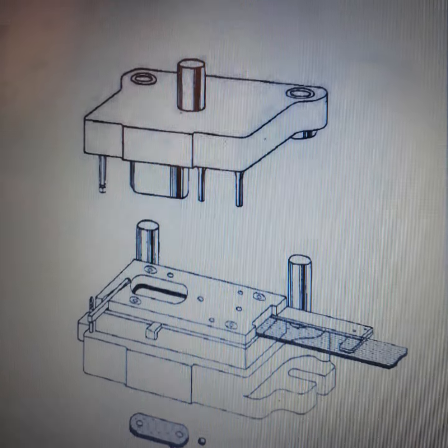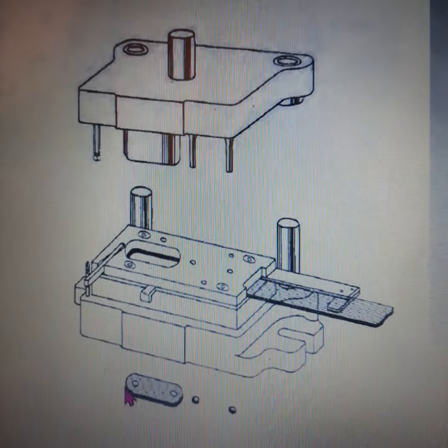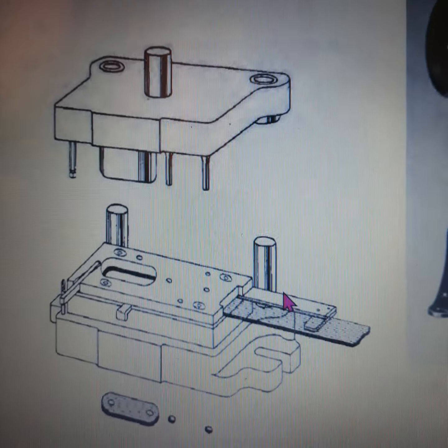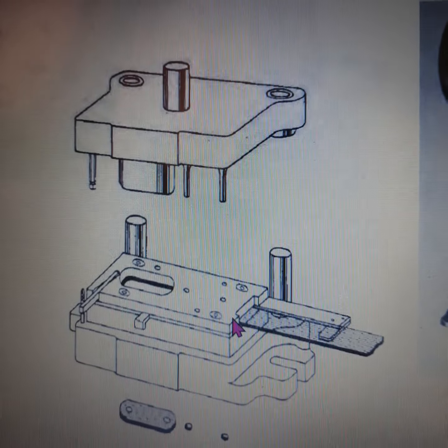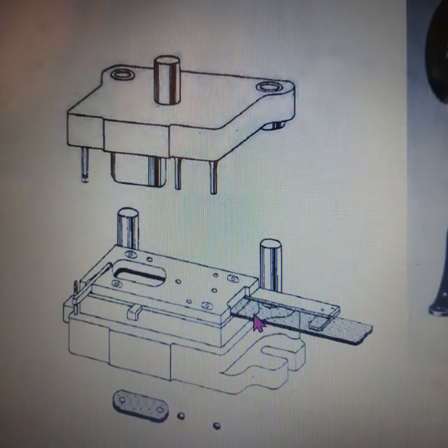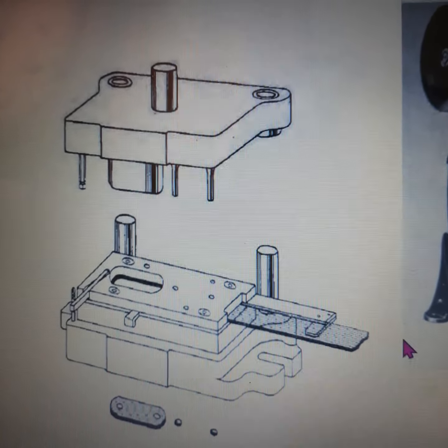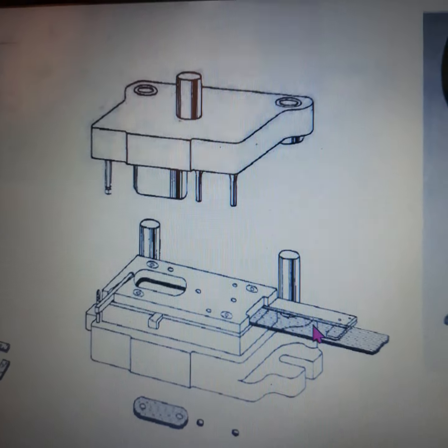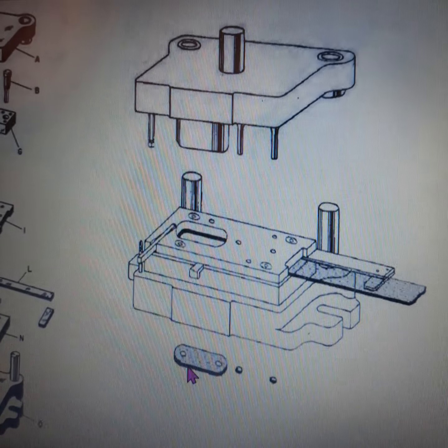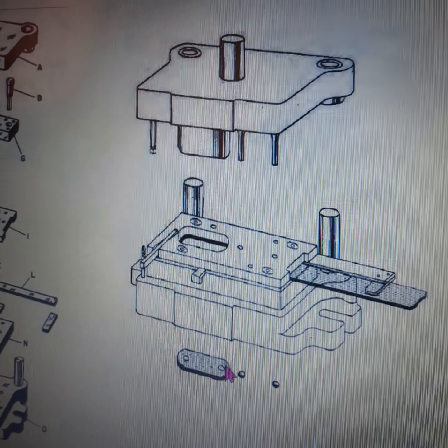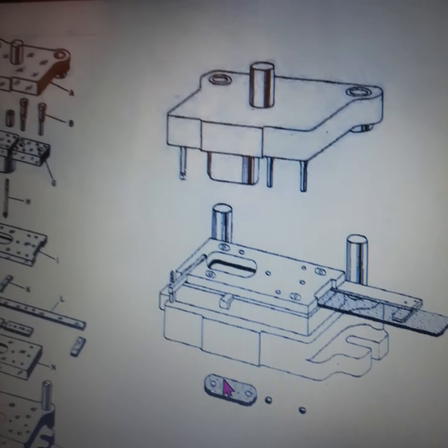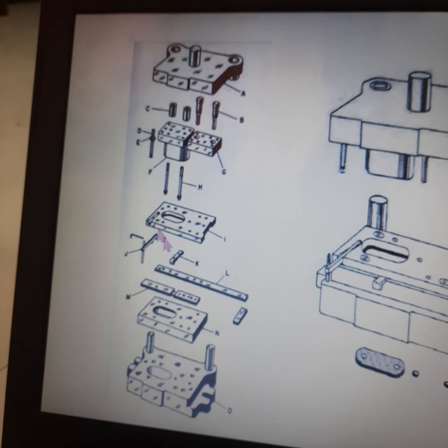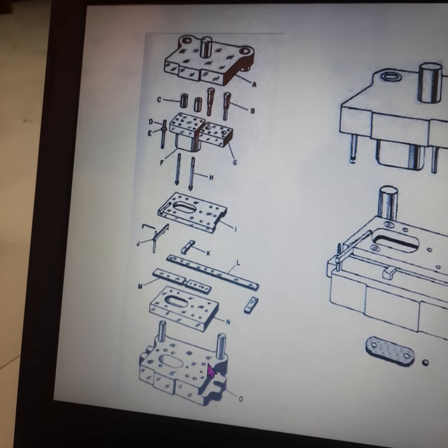The raw material for producing this sheet metal product is a lengthy strip. We call this the feed strip. This feed strip we have to feed into the progressive tool, and out of this feed strip we are going to produce the sheet metal component to the required shape and size. The exploded view of the progressive press tool is shown in this figure.